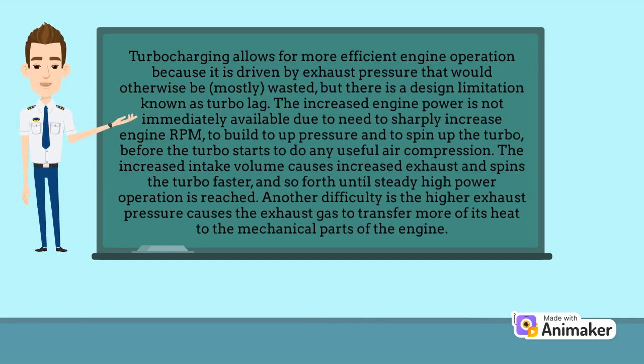Turbocharging allows for more efficient engine operation because it is driven by exhaust pressure that would otherwise be mostly wasted. But there is a design limitation known as turbo lag. The increased engine power is not immediately available due to the need to sharply increase engine RPM to build up pressure and to spin up the turbo, before the turbo starts to do any useful work.